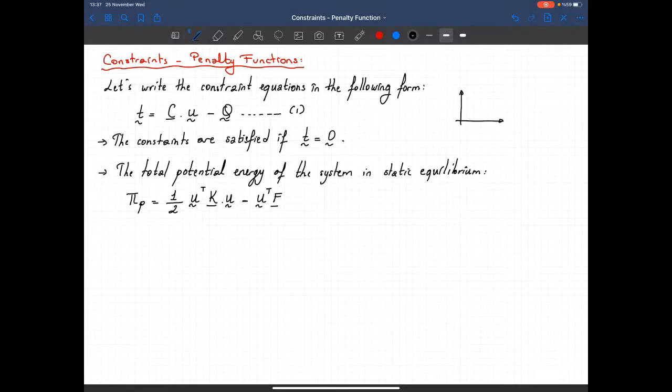So this is the internal energy, and that's the displacement. We see a relationship like that, right? The magnitude of that is equal to K times U. I'm just doing it for a single degree of freedom system. The strain energy is the area under this triangle, which is 1/2 times K times U, right? So I just write the same thing for a multi-degree of freedom system.